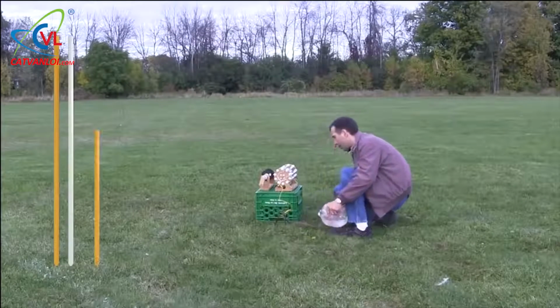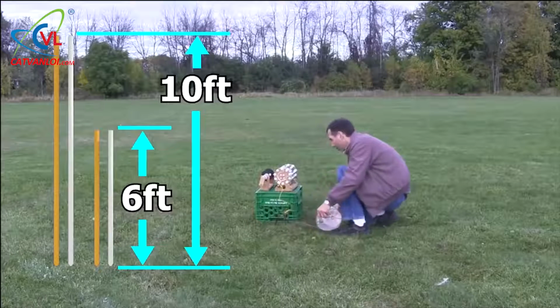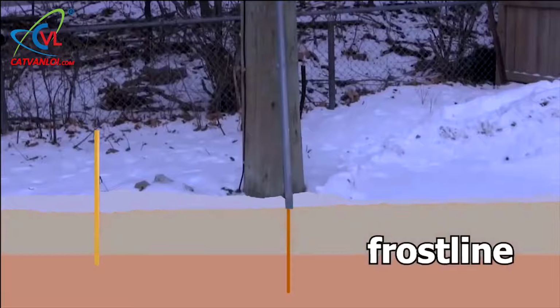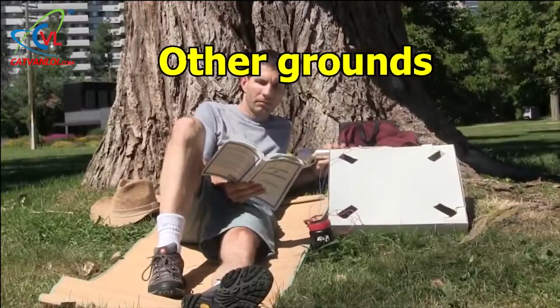You can buy copper and galvanized steel rods that are around 6 to 10 feet long, that you can pound into the ground. But keep in mind that cold ground lowers the conductivity, so make sure to drive it below the frost line for winter use. Besides the ground hole and the power socket, where can we find a ground to use?